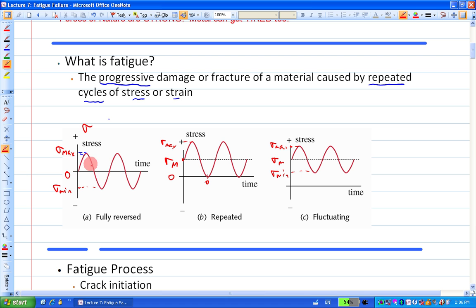However, because of this cyclic kind of stress, the material actually fails, even if the stress is well below the yielding strength. The reason is basically that it's not static, it's cyclic loading. So that's the danger of fatigue failure. When fatigue failure happens, it generally causes a catastrophic failure. I'll give you some cases, some pictures shortly. So guarding against fatigue loading is an important concern that you have to consider when you design things.